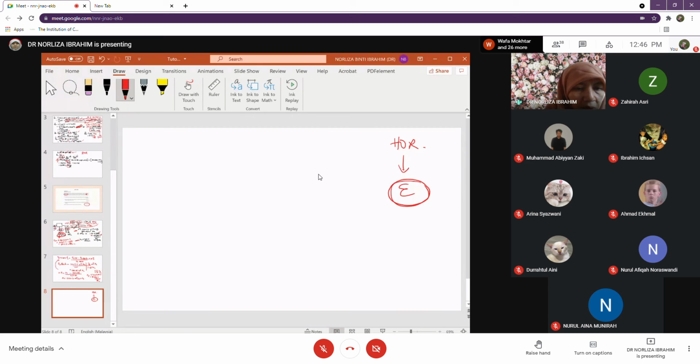So we go to SO3, because the SO3 flow rate is already given. SO3 in the product is equal to SO3 in the feed plus the extent of reaction. In the product you have 1500. In the feed, 0, because you do not feed SO3. SO3 is your product. So your extent of reaction is 1500 mole per minute.